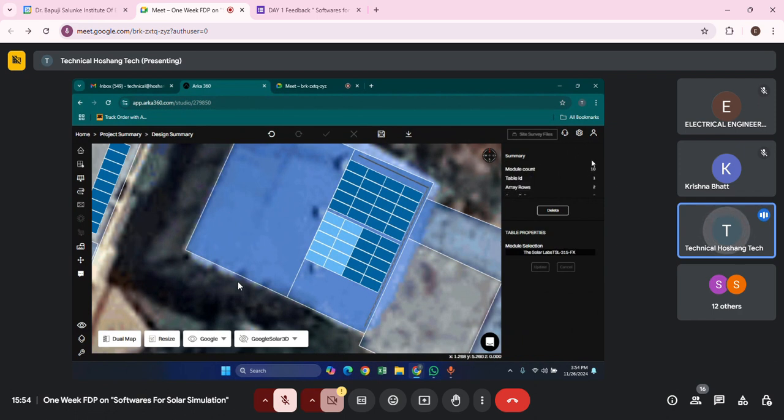While selecting the table, you have the total module count, and also the length of the table, which is 4 meters, and 5 width. So this way you will have 4 meters, 4.9, and this will be 5 meters properly. The length of solar panels is almost 998 mm, which comes to almost 1 meter. So this will be 5 meters, and the height of the panel is almost 2 meters, in mm it is 1986. It is the glass size, so you can add almost 2 mm as an expansion gap.